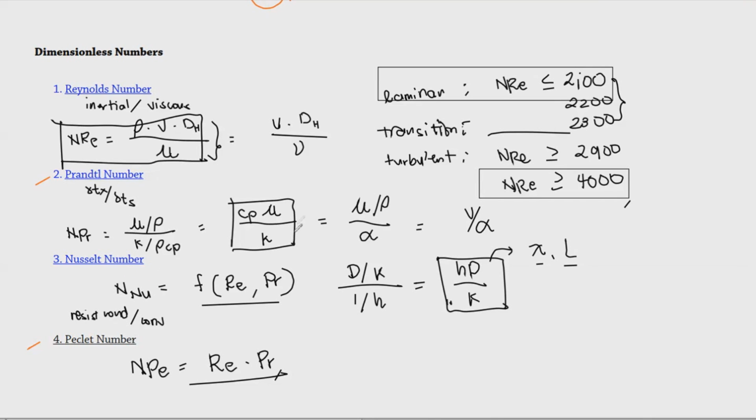The Nusselt number will give you very specific equations that vary depending on the condition. That's why I presented different kinds of free convection and natural convection before, since we'll be using a lot of the Nusselt number here. In today's video, you will learn how to review the Reynolds number and the Prandtl number, how to solve for them, and then the Nusselt number, and how to use it in computing for H. Since, as you can see here, we have H.